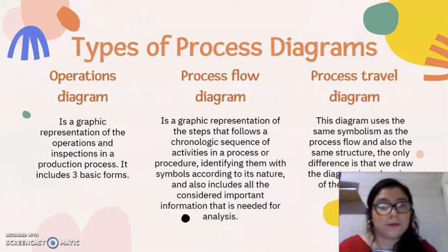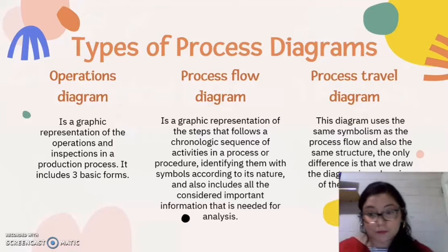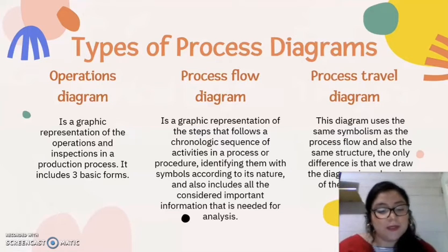First, I want to give you a quick summary of what process diagrams are. They are graphic representations that give us a clear perspective of the processes, including materials, time, distance, and others. All types of diagrams are composed of three elemental parts. First, the header, which contains general information like the company; the body, that is composed according to the process specifications; and the summary, which includes mostly the time to calculate the efficiency of the process.